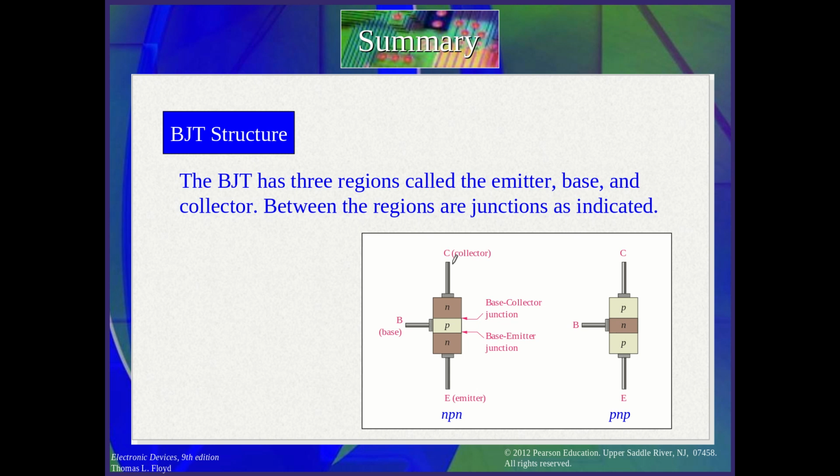Then you get the IC for this transistor, which is 2.09. So the IC here is less than the saturated value, so it is not saturated yet.